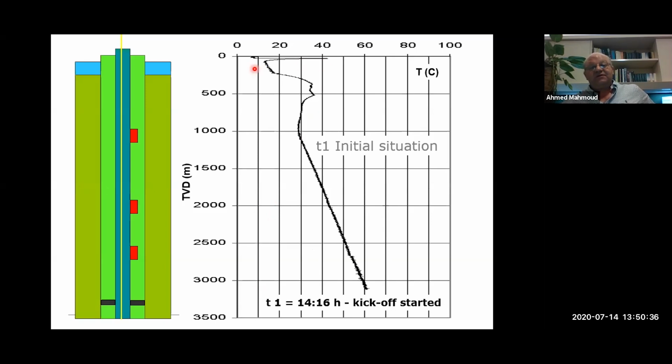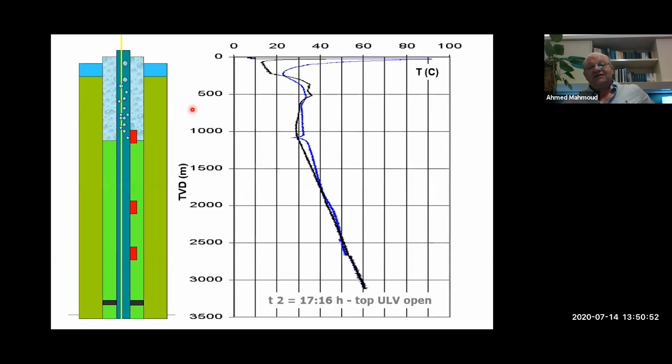And in this example, you have a well with, let's say, 3 valves, and this will be the typical temperature survey. And this temperature survey at the beginning, before I start, it's okay. And then we start the gas injection, I start to inject gas in the annulus, and the valve opens and the bubbles start coming in, so the hydrostatic pressure starts to reduce.